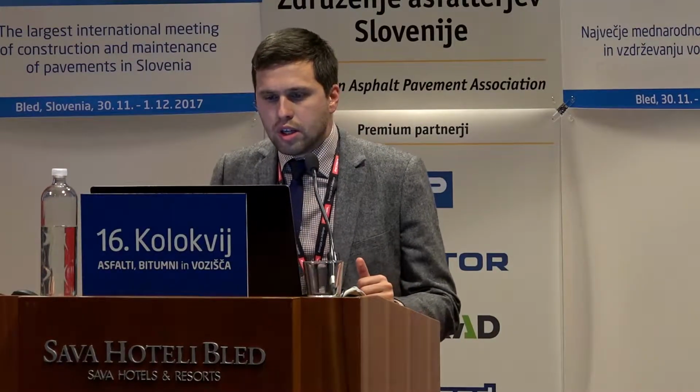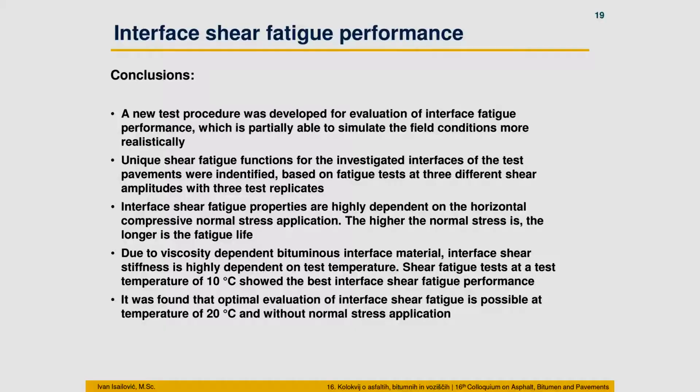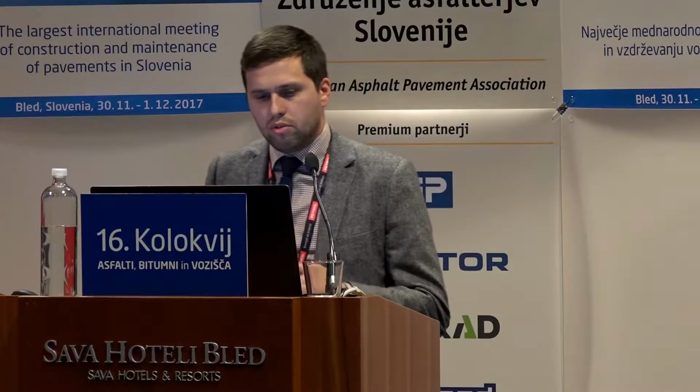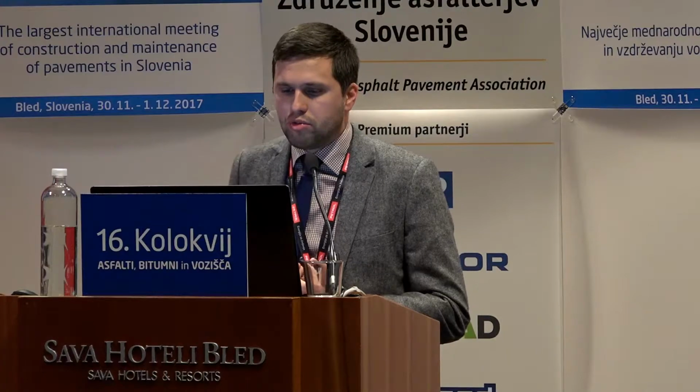Therefore, the following can be concluded. We developed a new procedure for evaluation of interface fatigue performance. We also obtained unique shear functions for the investigation of fatigue. Also, we saw that these parameters are highly dependent on the compressive normal stress application and also on temperature. And as a conclusion, it was found that optimal evaluation of interface shear fatigue is possible at a temperature of 20 degrees and without application of normal stress.